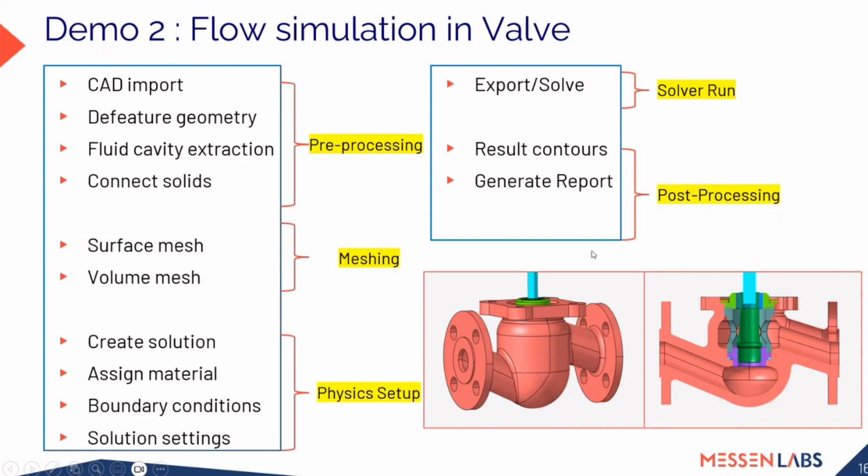So it is not just about one simulation. We need to do the simulation for various plug travels. Currently, it is in the closed position. We need to see the flow behavior inside the valve at various plug movements. So what if I have a script and run it again and again? I don't have to worry at all. So let me do that for you.